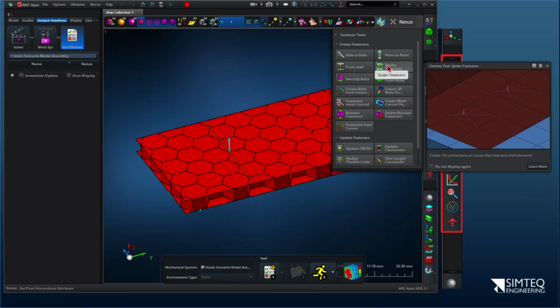If those connectors are at arbitrary locations and not close to a node, these spiders can then attach the adjacent nodes of a single element, or however you specify that, so that the load is not transferred at a single node, but maybe over a larger area.